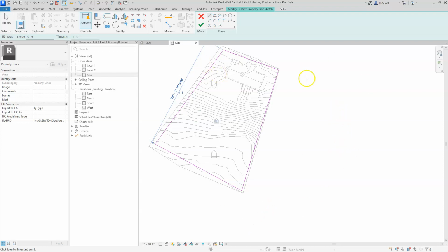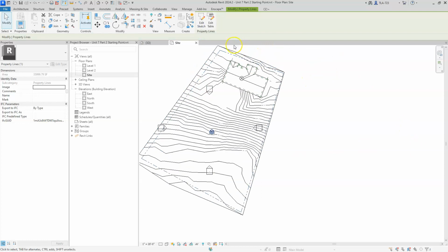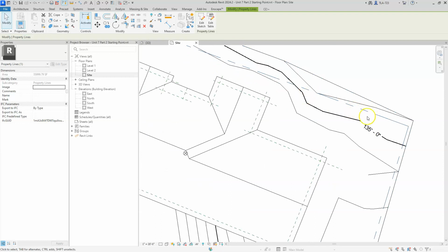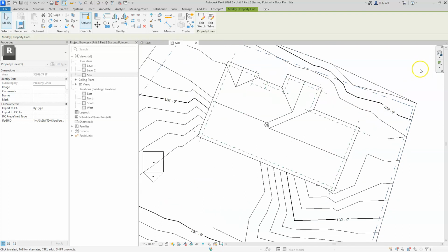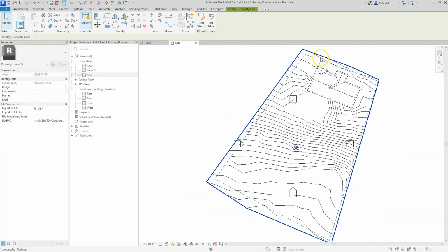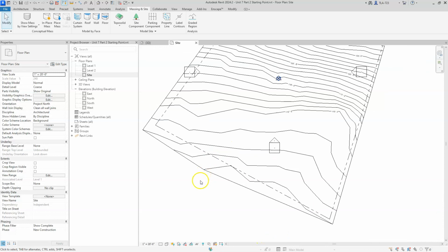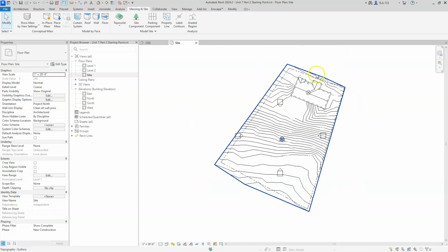All right, so once those 4 lines are created, we can click Finish. And now we've created those property lines, and you can actually see the property lines. They're showing up just like you would expect property lines to, with that double dash or phantom line style. And if you deselect, you can see it just goes to black. Those will print as they should. Okay. And that's it. Now you've got a property boundary on that thing.